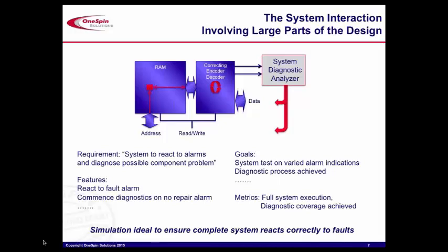And essentially what would happen is the alarm bits coming out of the encoder decoder would be forced to a certain level, and then the operation of the diagnostic system would be analyzed to make sure that the memory was fully cycled, and that a fault inside the memory which was seen to be permanent, which you could do by changing the design, would trigger the component to be noted as faulty, versus a temporary injected fault, which would be noted as something that just happened because of the environment, and not because of a faulty component.